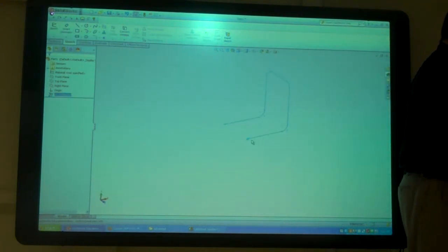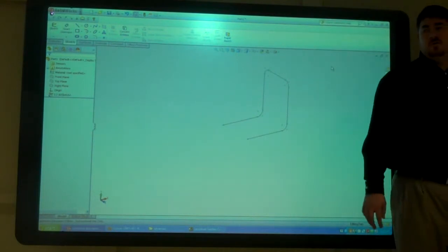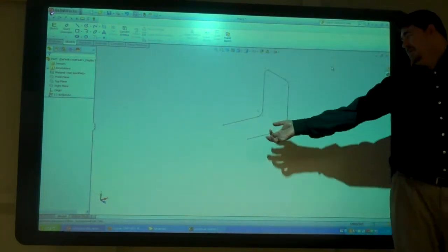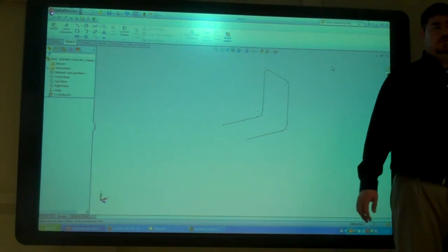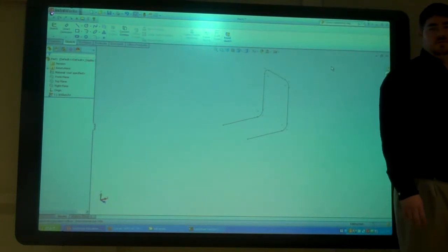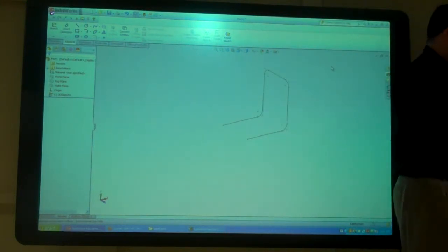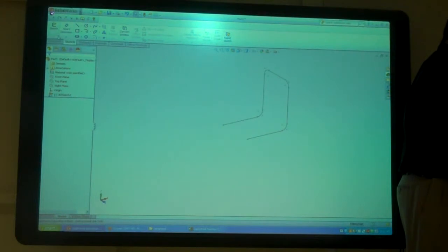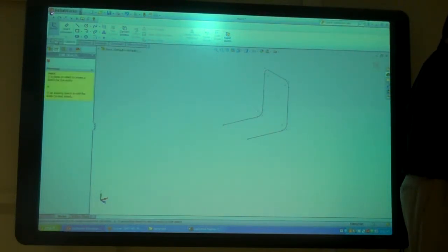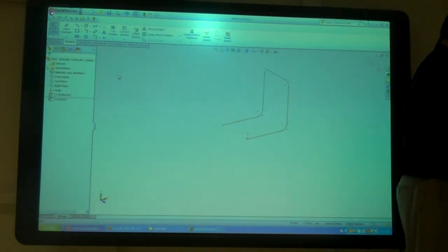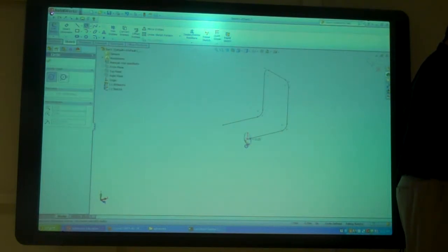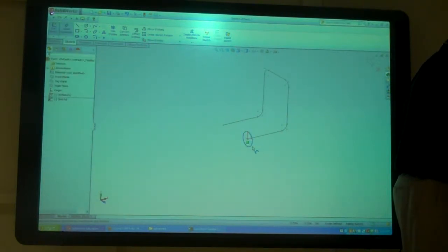So if I want to make my circle, what do I need to do? So if I want to make that a round piece of element or something. Put it on your plane at the bottom, right on the edge where you started. So I can do another 3D sketch, or I can just do a 2D sketch, right? I can just sketch. If I started that on this plane, draw a circle right on the tip from that point.